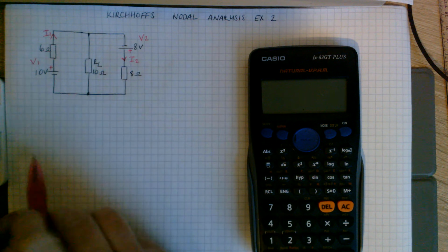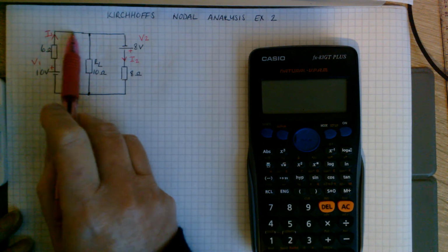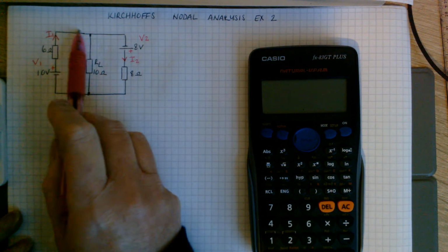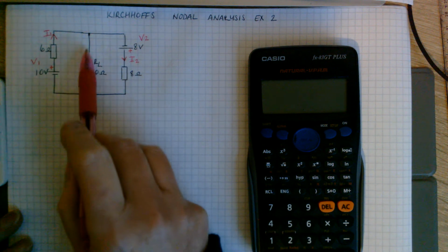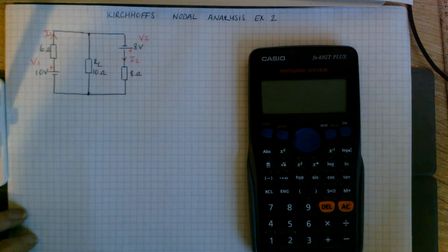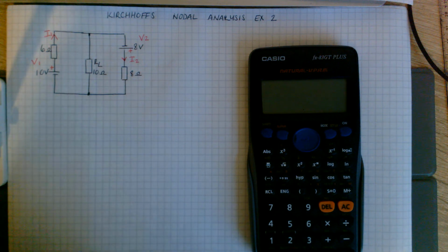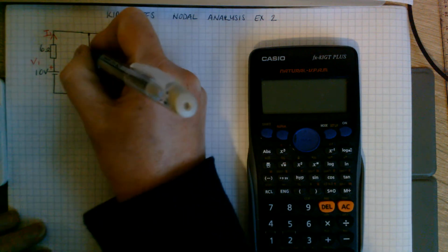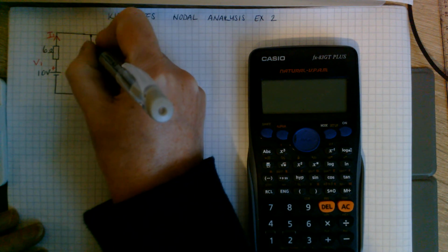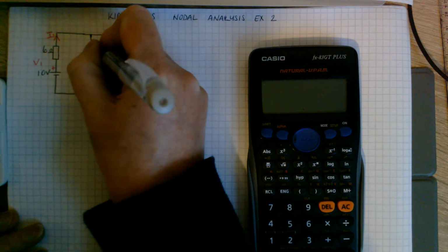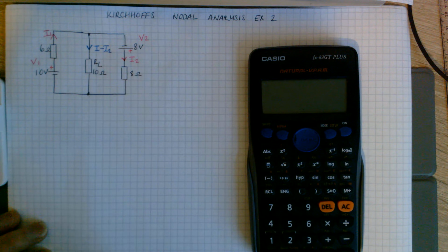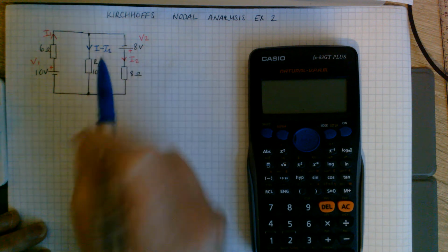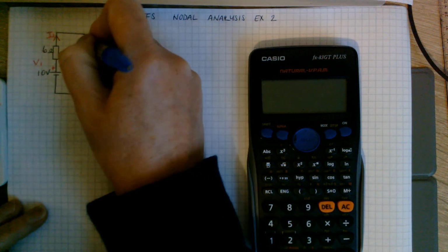I2. What you should notice when these come round and hit this junction is I1 would be coming down the way and I2 would be coming up the way. So you have a choice at this point. You can either describe this current coming down the middle as being in this direction and being I1 minus I2, because I2 would be coming up the way, so in the negative direction.